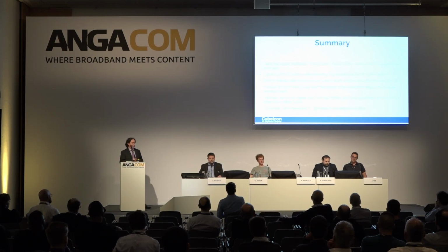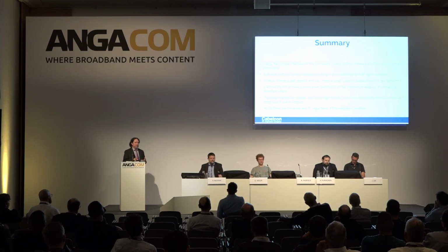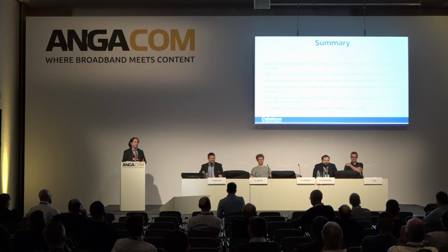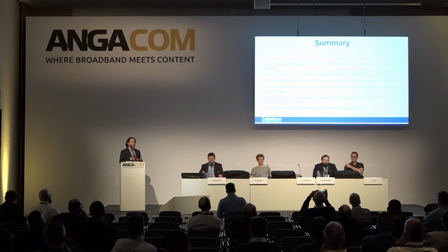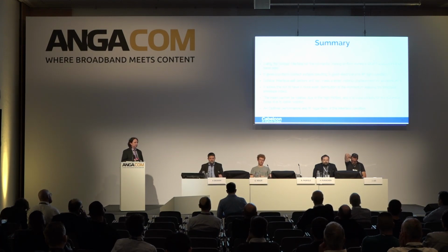So before I go too far over time, I will do a very quick summary. We've tried to show very briefly here that by keeping the connector within the confines of the SCTE specifications, but having a subtle change to that interface, we can overcome some of the issues that have been seen. We have that self-centering, we have a small material displacement, especially with the hard brass connector, and that can help with some of these softer materials on the ports. Overall, we're just trying to make a better mechanical, which therefore leads to a better electrical connection as well.